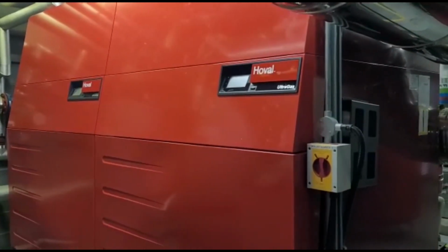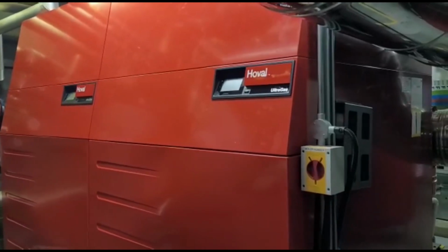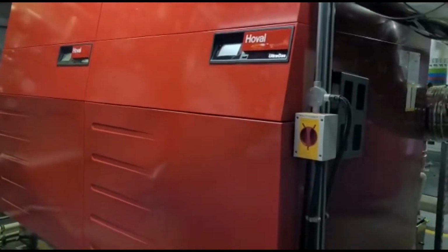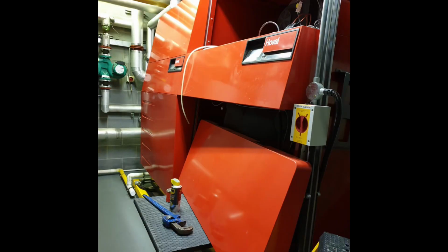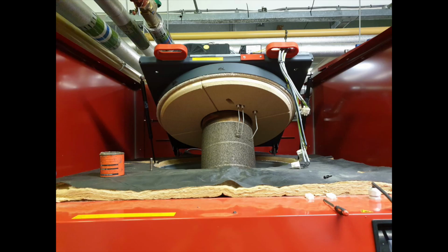I'm not going to open them up because there's all kinds of fiddly little screws, but basically take this front panel off here and a step comes down. That's so you can get up to the top, take that top panel off and some sliding bits, and you get to all pressure switches and burner and fan and gas solenoid and all that lot. And it's basically just a big dustbin lid with burner and everything sat on top of it. That's all it is. Pretty simple really.